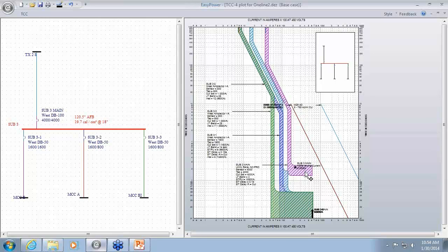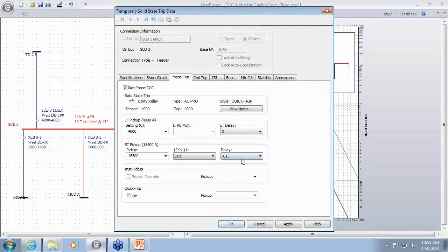So by just changing the device to get a different curve, it allowed slightly better settings, which we were able to reduce the incident energy by half. So sometimes maintenance mode may not be what you're looking for. You may change out a device, or a trip unit, just for a different trip function, or different curve type.